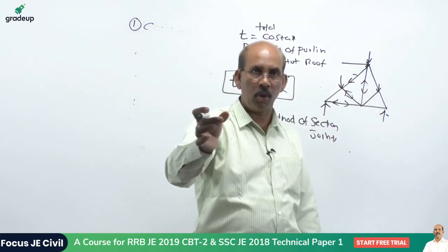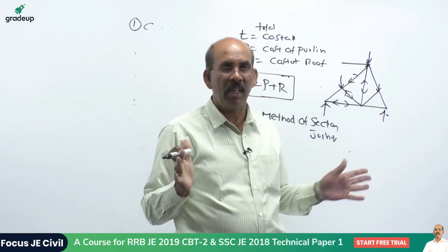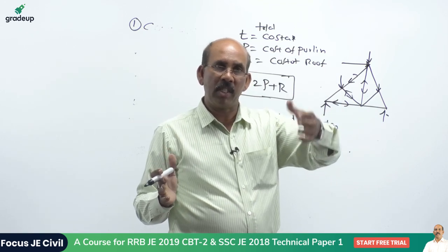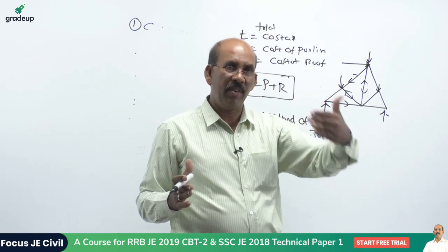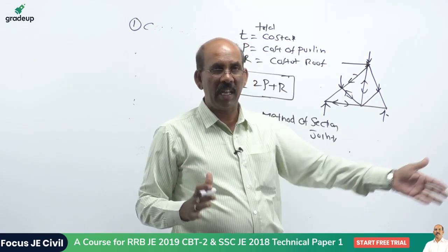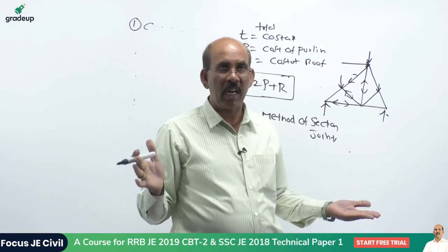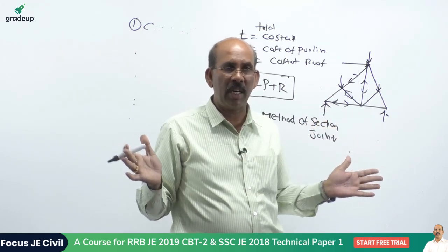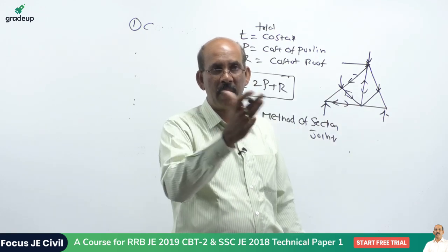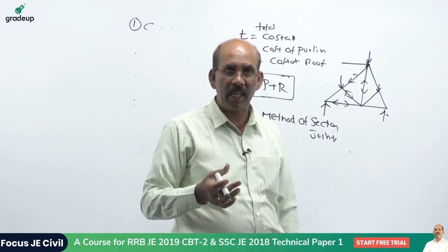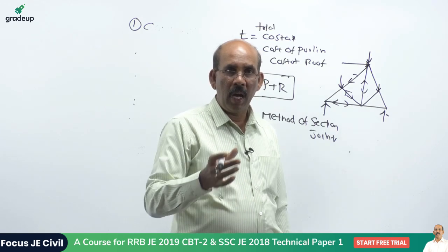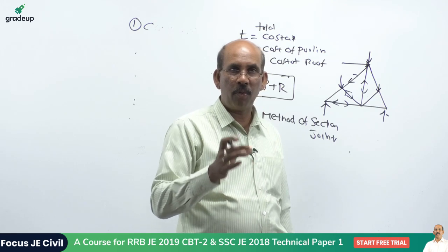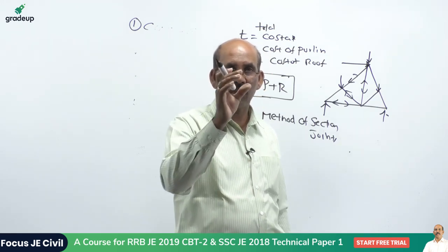From your analysis you calculate the magnitudes of the forces, and also the nature of the force, whether it is compressive or tension. For a tension member, the net sectional area is used, and for a compression member, the gross. Once the load is calculated, tension member design is different from compression member design. Mr. Sushanta Garai, I think it is clear how to find the load according to the wind code.